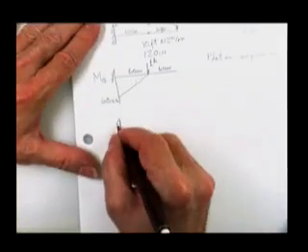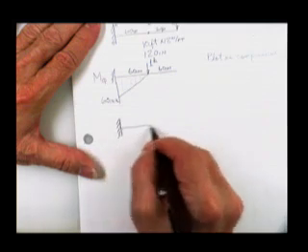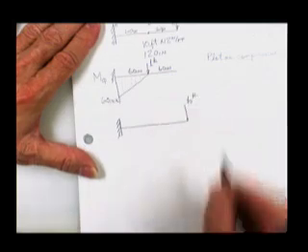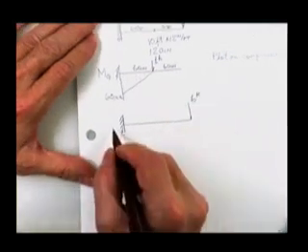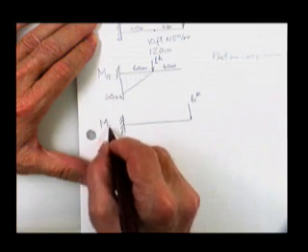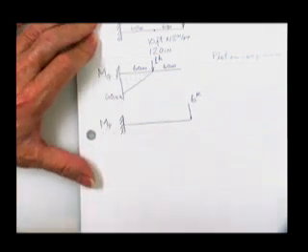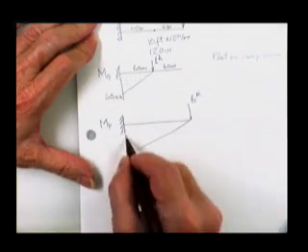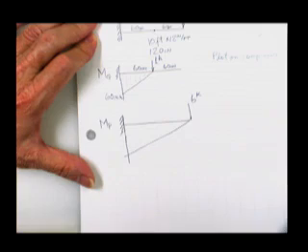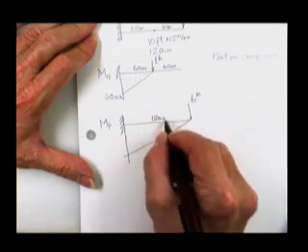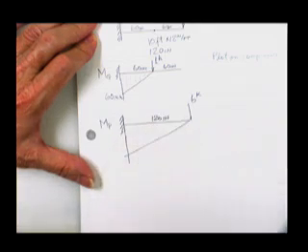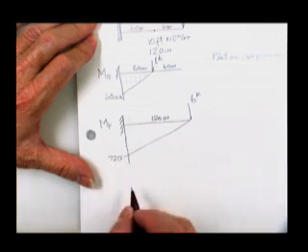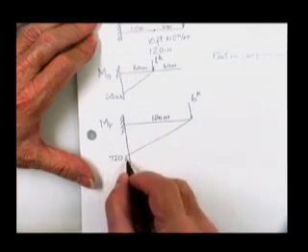Next, I'm going to draw the beam redone. And I'm going to put the 6-kip load out on the end. And this will be M due to the real loads. And the moment diagram looks like that. It's 120 inches. 6 times 120, 720 inch-kips.